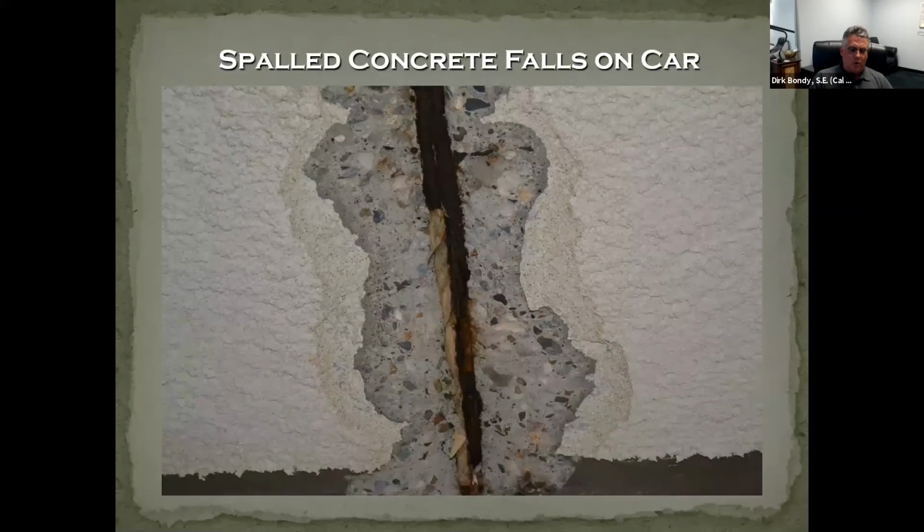This is one of the more dramatic things right here in Newport Beach that we got called out to. This was the slab up above. I'm taking a picture looking up, again, at paper-wrapped tendons. This is what you can expect to see if the building was built in the 1970s. It's not plastic, it's wrapped in paper.